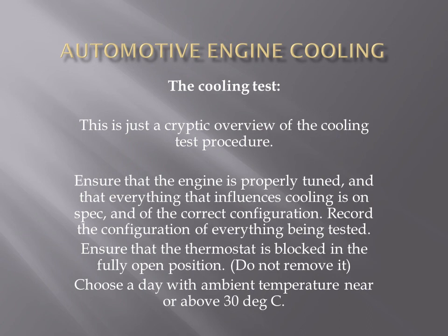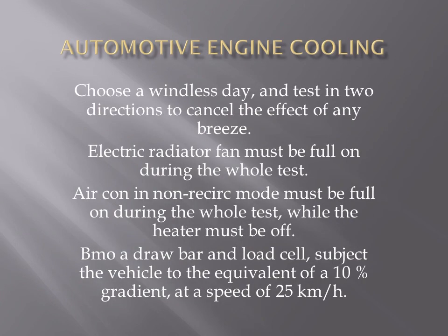The coolant test. This is just a cryptic overview of the coolant test procedure. Ensure that the engine is properly tuned and that everything that influences cooling is on spec and of the correct configuration. Record the configuration of everything being tested. Ensure that the thermostat is blocked in the fully open position, usually 5 to 6 millimeters, but do not remove the thermostat. Choose a day with an ambient temperature near or above 30 degrees centigrade. Choose a windless day and test in 2 directions to cancel the effect of any breeze.